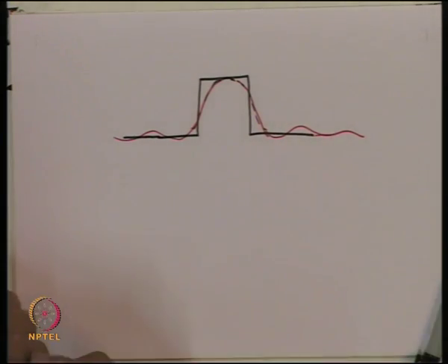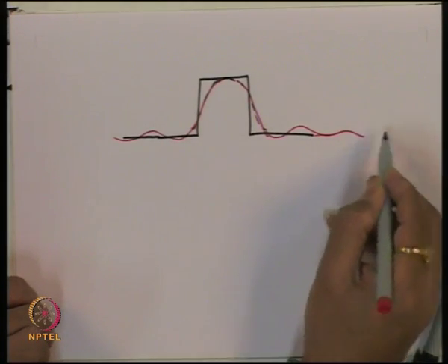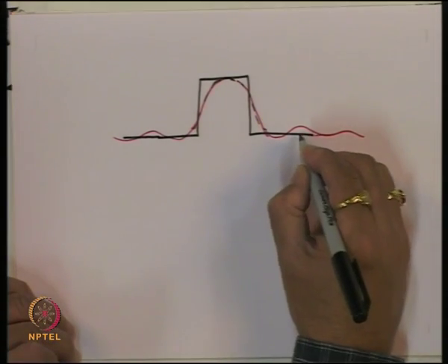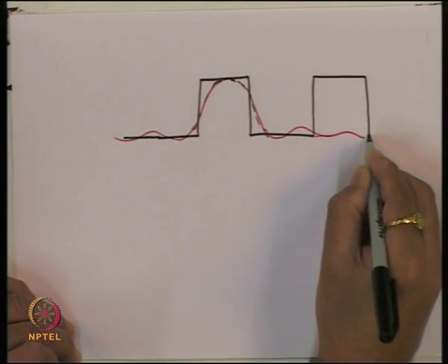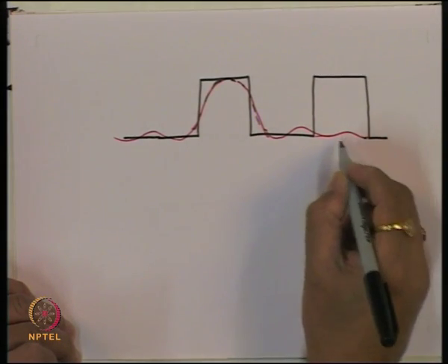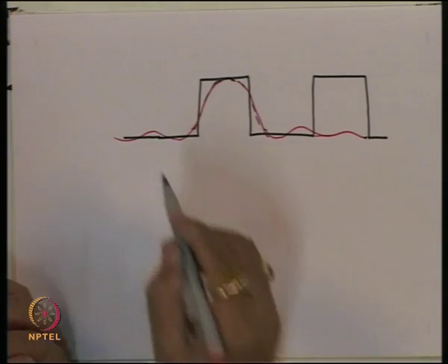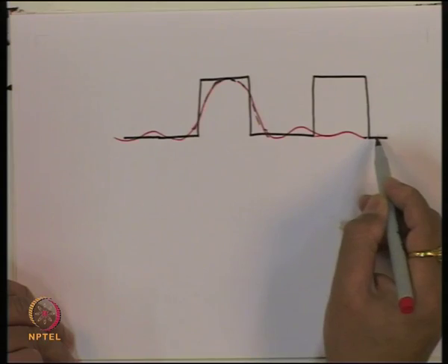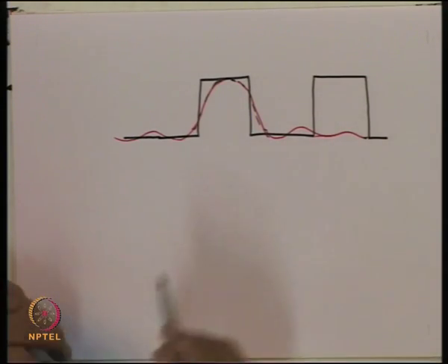Obviously, this signal which ideally should have been 0 now has these fluctuations. So, if you have another bit present at this location, this signal is going to superimpose on this. This phenomenon is what is called the intersymbol interference. So, we are transmitting this bit, and this bit is now going to create an interference at another bit which is separated in time.